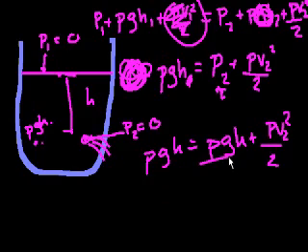And what does that mean? That when I say that pressure at the output of the pipe is rho GH, that means that I'm applying some pressure into that hole. And essentially, that pressure I'm applying into the hole is exactly just enough to offset the pressure at this depth. And because of that, none of the water will move.